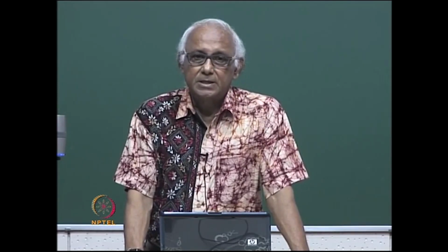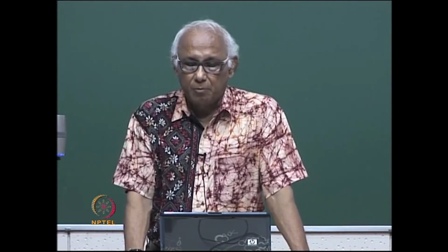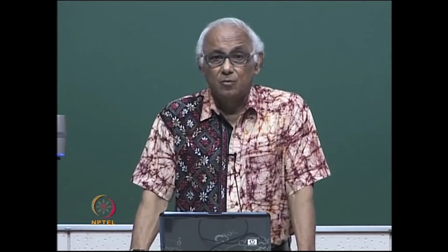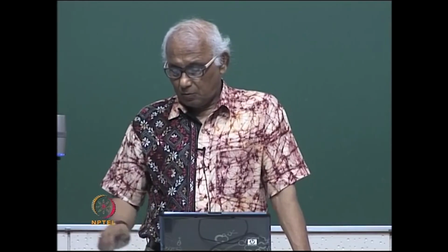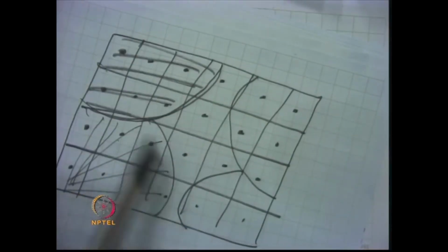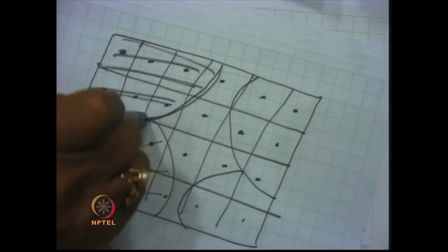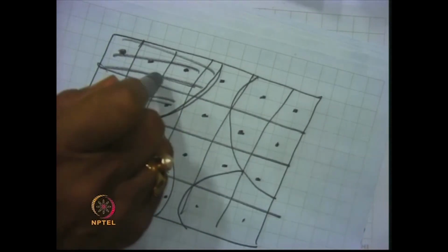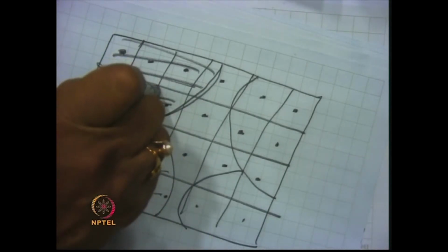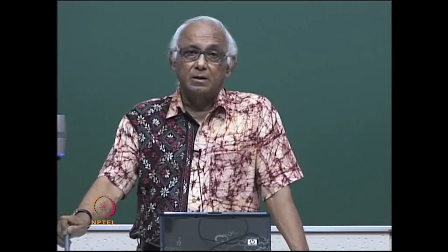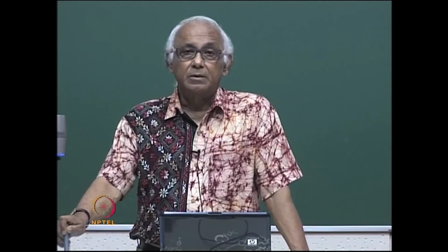These two parameters are very important, because for design purposes one should know what is the peak ground acceleration for which the structure should be designed in each sub region, and what is the likely amplification factor for that region because of the soil condition.